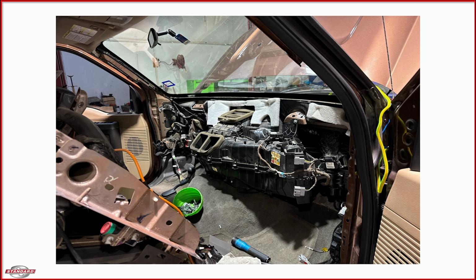When you find yourself in this position, and the vehicle is an older vehicle, confirm the actuator first, and also consider replacing the other air door actuators in the vehicle. With age, plastic gears can begin to weaken. Air door actuator damper pads can become crushed. Actuator motor positioning can become an issue, amongst other possible problems.